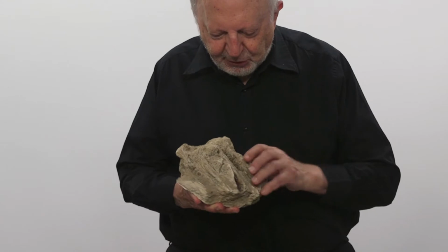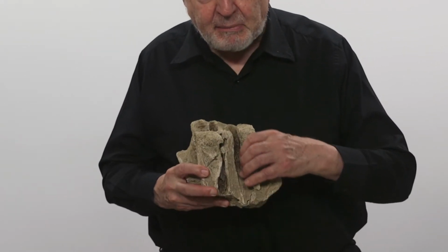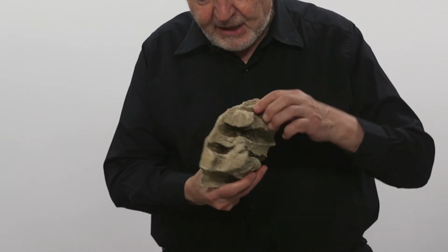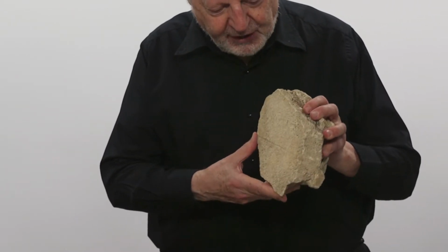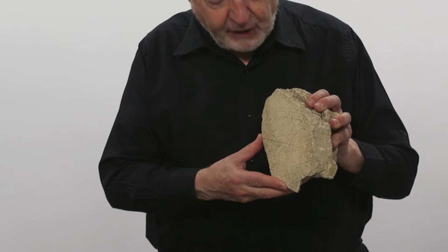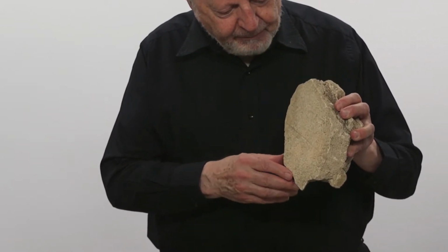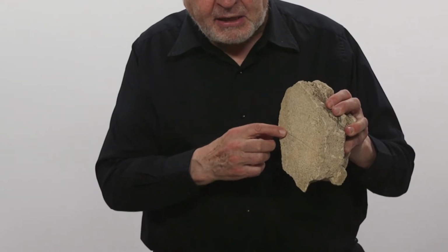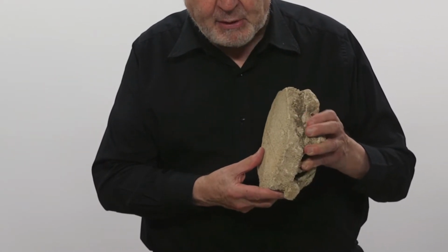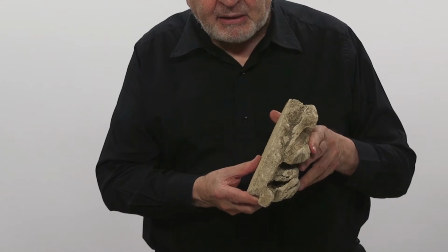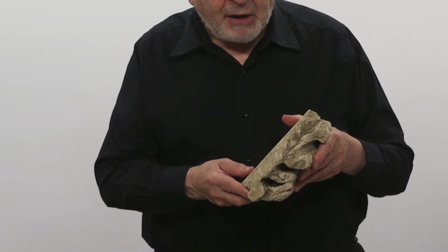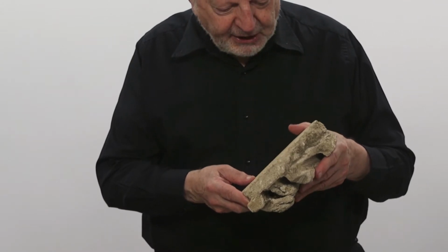This is an early example. It's a very primitive building because you can see these are the remains of timber saplings. So it's timber saplings on the outside of the building running horizontally, and then this on the face, smooth facing, which looks quite sophisticated when it's finished because it's been made totally smooth and ruled in lines to look like the joints in masonry. And that's the way lime is normally used, to imitate a masonry building. And sometimes it's had a coloured wash, sort of brown or creamy coloured wash to enhance that effect.